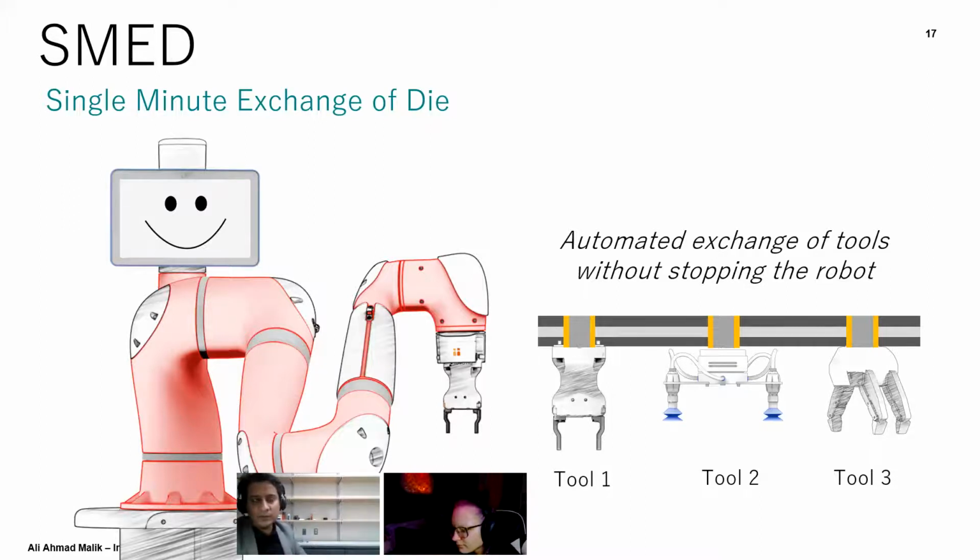So in terms of robotics, we can say that these tool changing devices are aligned with this SMED concept, because they enable us to change the tools without needing a screw driving tool to open the screws, close the screws, and get aligned with the new tool. So all this tool changing can be done more automatically with these tool changing devices. And this is aligned with the lean concept of SMED as well.